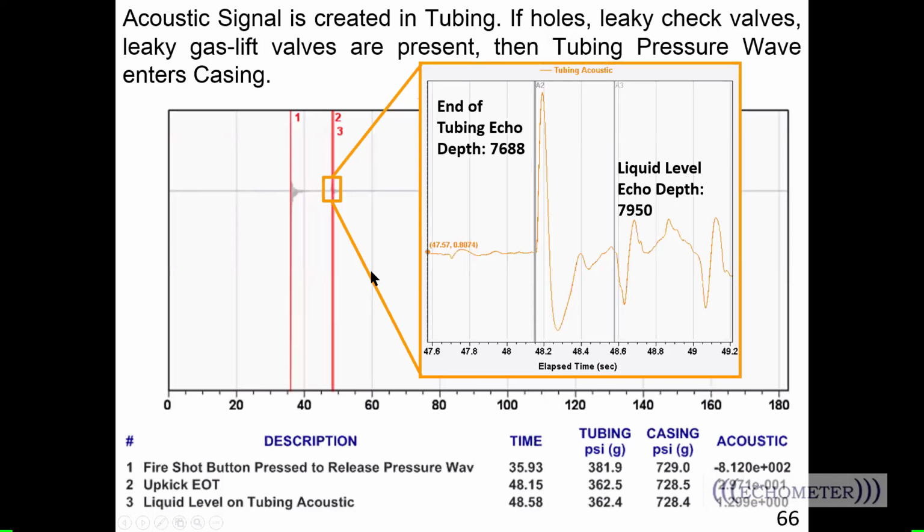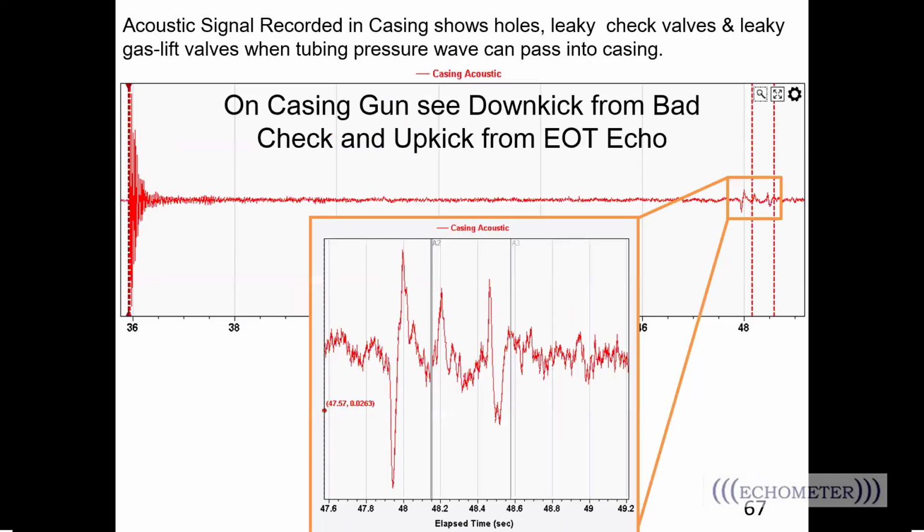All right, so it does take a little bit more work manually if you have the wireless equipment and you're using the plunger tracking feature to perform your dual shot. There's a zoom feature where you can go in and just specifically highlight that fluid level shot. So there are some tips and things that we can help you out with getting that dual shot analyzed. All right, so here you just see a close-up of the dual shot.